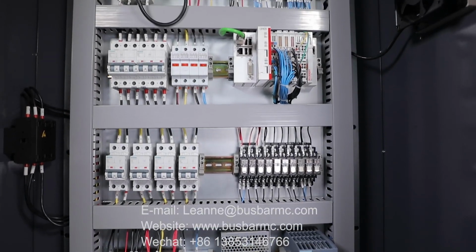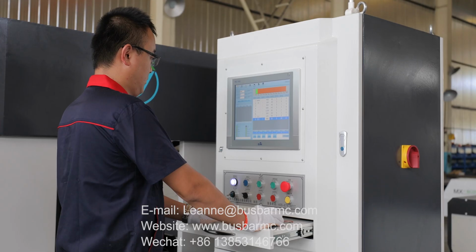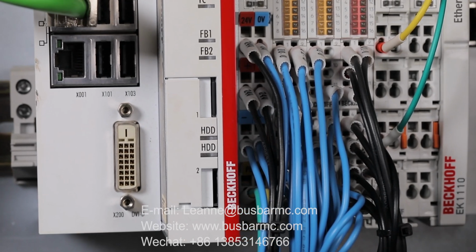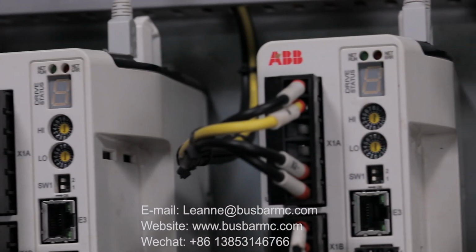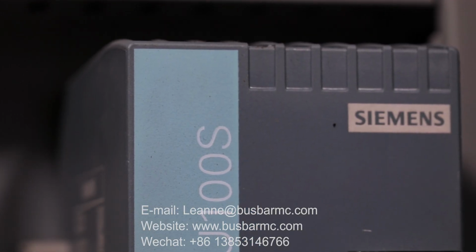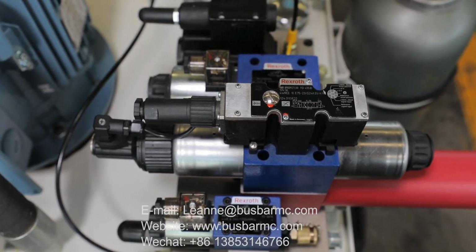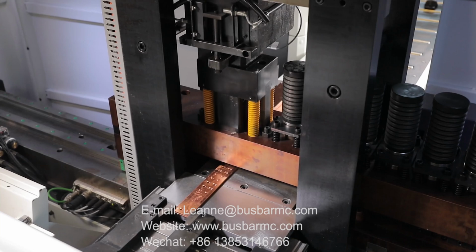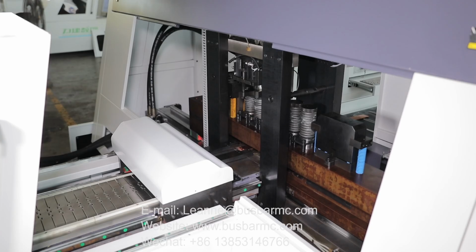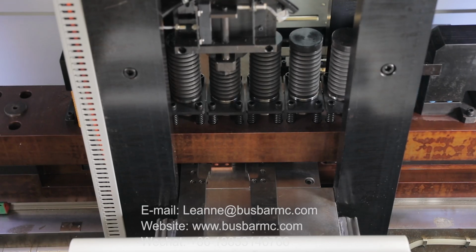The CNC electrical control system of this machine consists of controller, servo system, man-machine interface, detection device, etc. The German original Beckhoff brand controller, 4-bus controlled ABB brand servo motors, and German Balluff linear displacement sensor guarantee the stability of the machine. The main stamping cylinder, controlled by the German Rexroth proportional valve, can reach up to 180 times per minute. The high-quality accessories guarantee the efficiency, stability and service life of the machine.